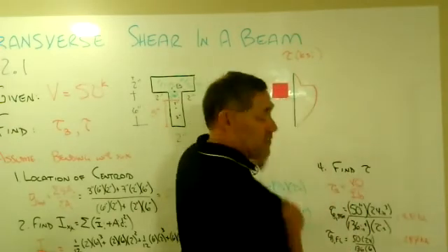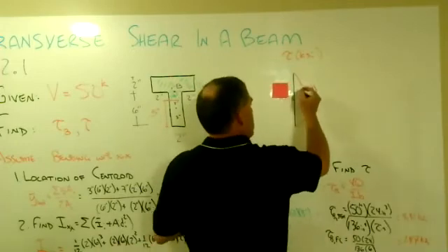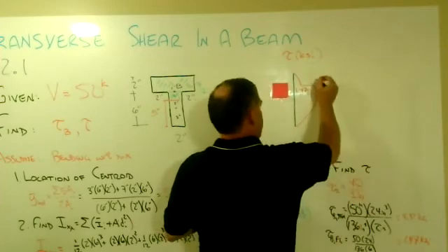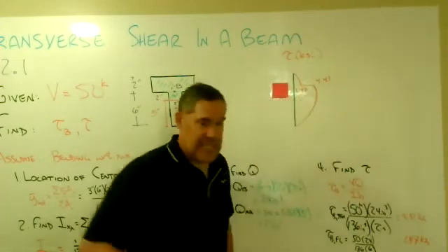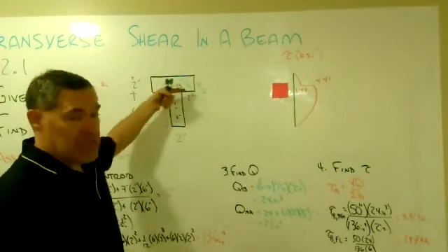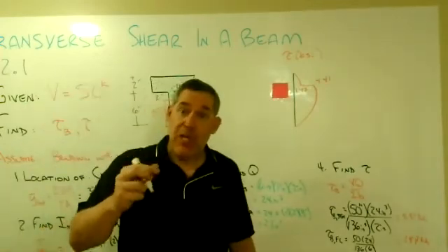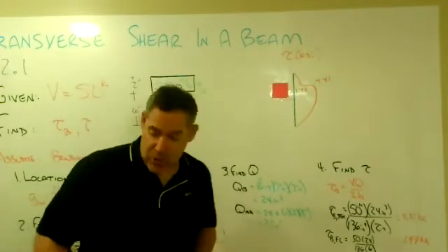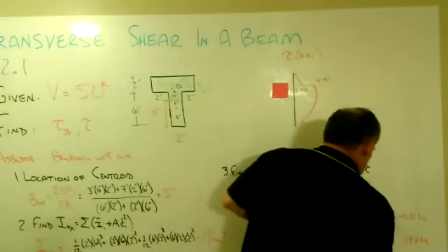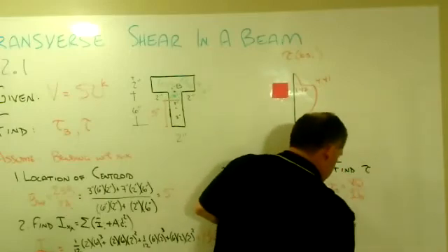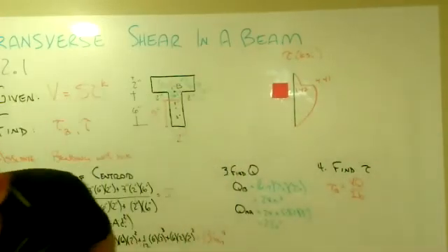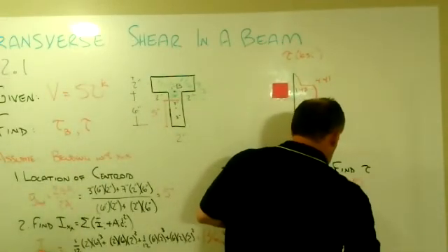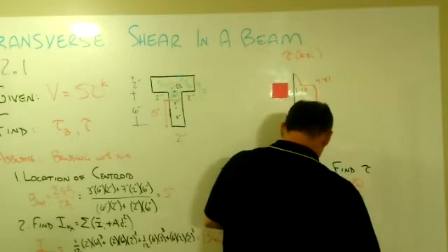Right, so up here in this variation that I drew, the lower value is the 1.47, the larger one is the 4.41. We have this immediate discontinuity that happens because the only thing that changes just a little bit above and below is that value of B. Okay, so that's for those two. For the neutral axis, it is of course a similar calculation. The only things changing are the Q and the B values, right? The I doesn't change.